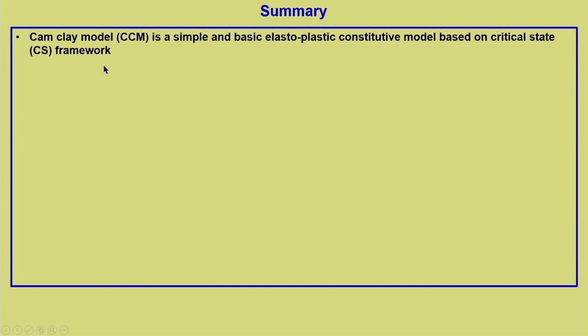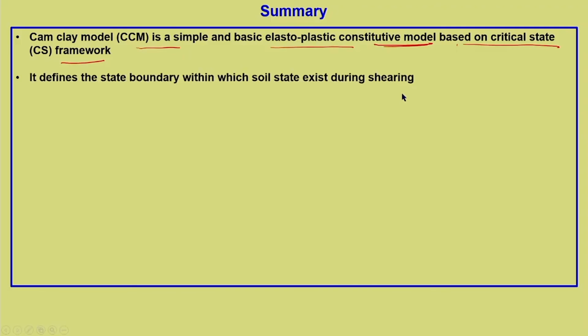The Cam-clay model, CCM, is a simple and basic elastoplastic constitutive model based on the critical state framework. Again, I would like to add a caution while saying elastoplastic constitutive model. We have not completed the entire constitutive model. We can say it is a constitutive model when there is a proper relationship between stress and strain. So, we have discussed the partial framework right now.